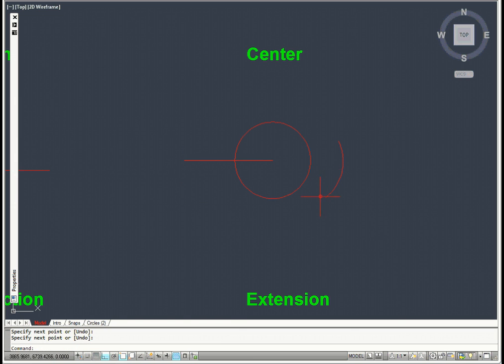Likewise with arcs, if you L enter, you can see a little inferred marker appear across here. It's actually snapping to the endpoint and midpoint of this arc. But if I move back to where that little red cross is, that will give me the center, and it'll pop up with a little tooltip to say center if you're not sure. So click again, and I've now snapped to the center point of that arc, and then to the midpoint of the arc.